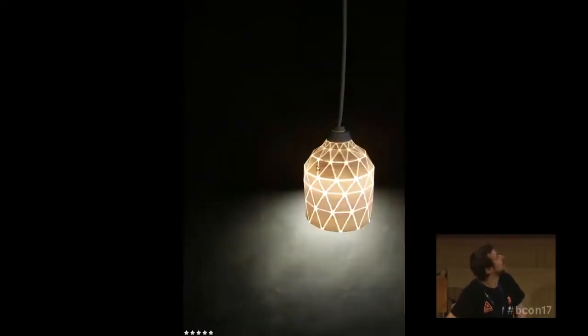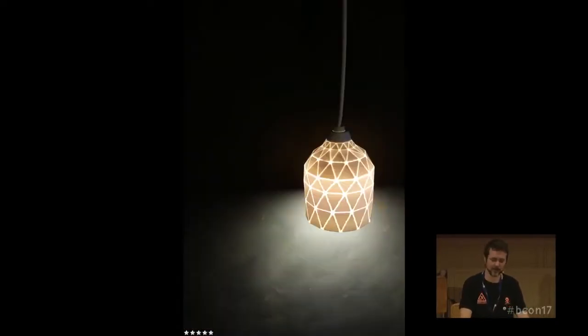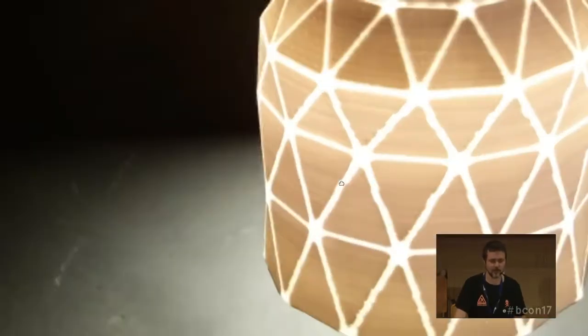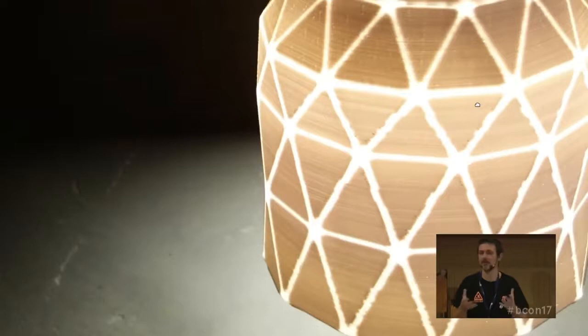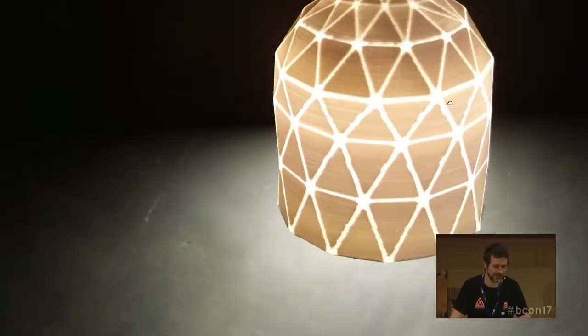I like this one because it shows the difference between what you design in Blender and what you get in 3D printing. In Blender everything is perfect, and when you 3D print it, there are some imperfections that I finally find more beautiful. This is very easy to do. It's a basic shape, a cylinder. Then you make all the faces triangular. You put a small displace modifier with a noise so that it's not so straight.